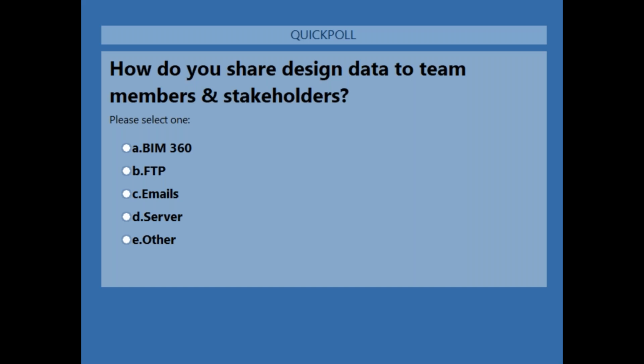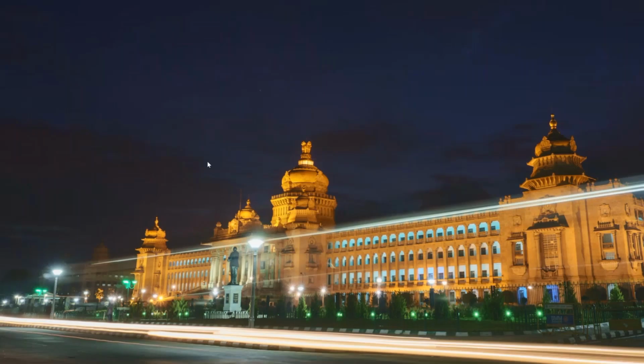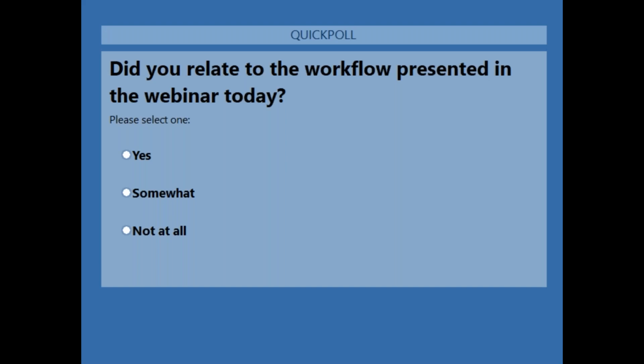AutoCAD to BIM 360, any relation there? Yeah, even AutoCAD users can use BIM 360. We have an application called locking, which locks the drawing files. When you're working on an AutoCAD drawing from the cloud, if someone has opened the AutoCAD drawing, it will show a lock icon, so others cannot make any changes there. So even for AutoCAD you can start using the document management module.